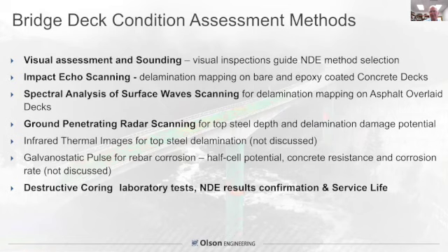So now the last thing we're going to talk about today is bridge deck condition assessment. Common problem: more than half of the maintenance money in the United States is spent on repair and replacement of bridge decks. So you can do it by visual assessment and sounding, typical chain dragging that people have used, or hammer sounding, for years. There have been studies that have shown that's subject to the accuracy of your ear and experience. And you can only hear about 3 inches deep into the concrete.